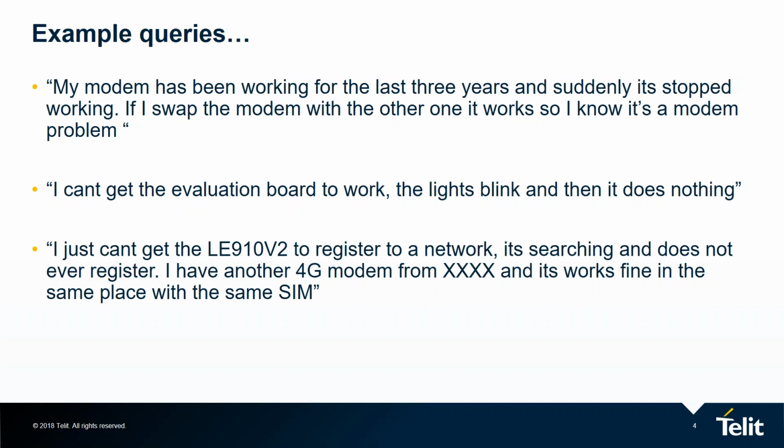I can remember one case where I spent quite a few emails going back and forth with one customer, and he was trying to connect to the USB interface. It was implemented on some test points on his board, and he was trying to connect there in order to debug. So he patched a USB cable into the board, and Windows was not enumerating. He was getting the ding when the USB device is detected, but there was no enumeration. The enumeration failed, and the drivers were not working.